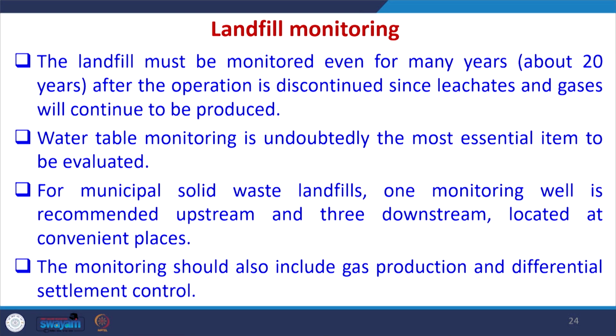Now, since a landfill operates for about 20 years or more, the landfill must be monitored even for many years after the operation is discontinued. Once 20 or 25 years are over, the landfill must still be monitored, since leachates and gases will continue to be produced. Water table monitoring is the most essential item to be evaluated wherever the landfill is.